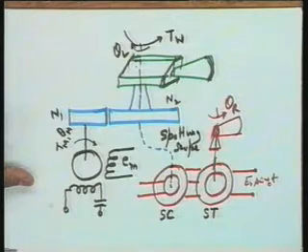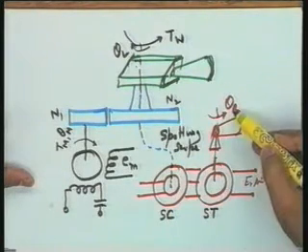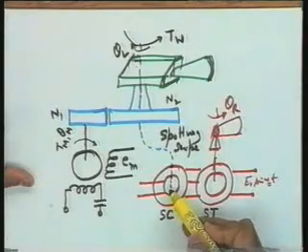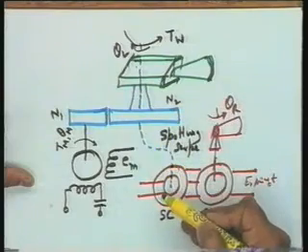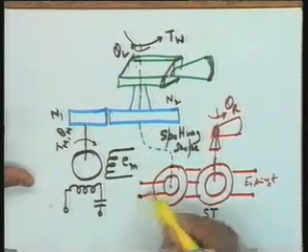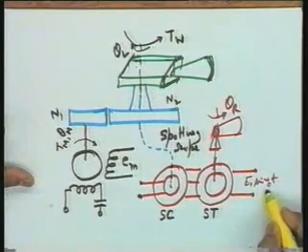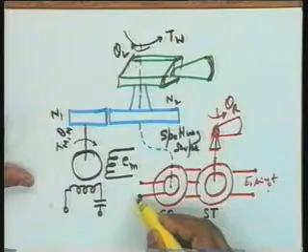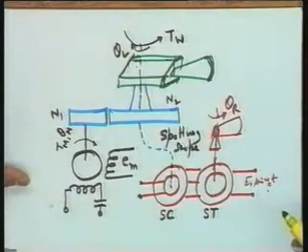I hope this is clear. As far as this synchro pair is concerned, the transmitter movement is given by theta_r, and the control transformer rotor movement is given by theta_L through a suitable mechanical link. So this particular signal is a modulated signal, omega_c being the modulation frequency, and the envelope is proportional to the error between theta_r and theta_L.